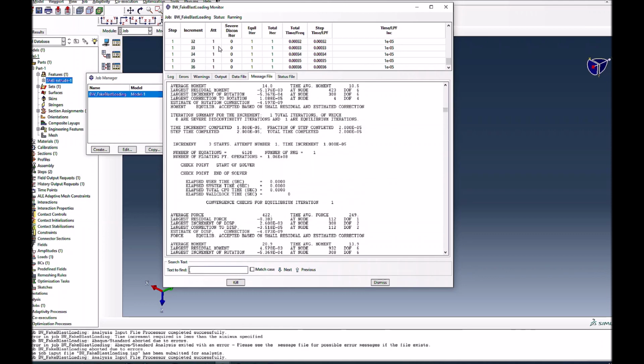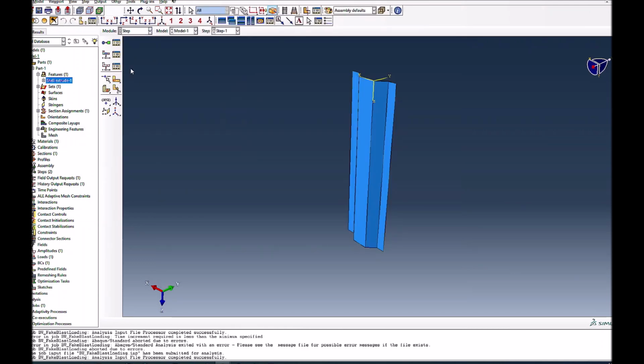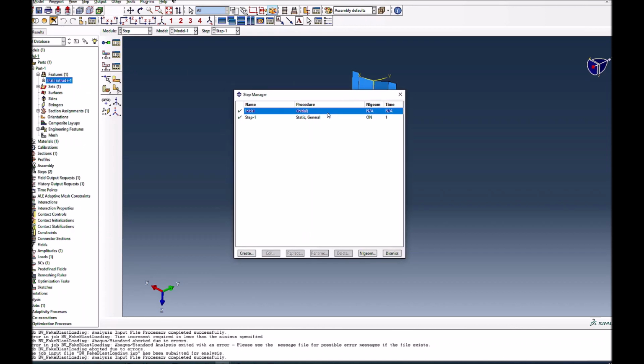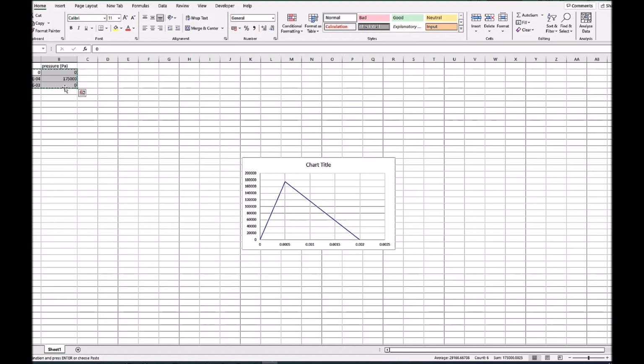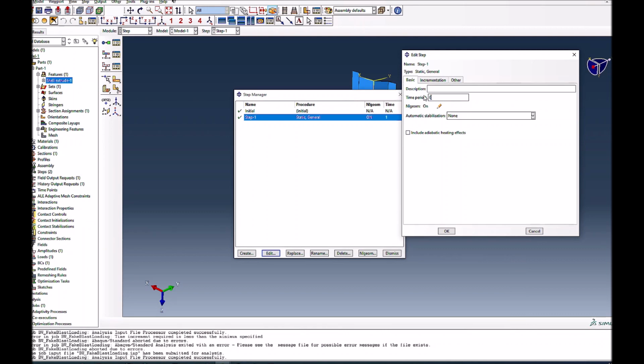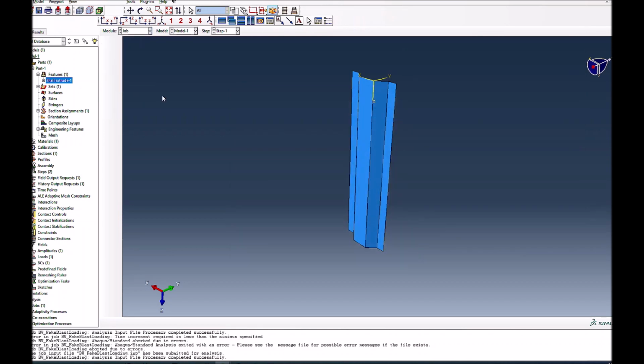As soon as we increase the thickness, it basically started working properly, and you can see it's going fine now, and it has to go up to, but I think we can stop it here. I think I didn't define the total step time correctly. So this total time should have been the same as what we have here, which is 2 exponent minus 3, right? So it should be 0.002. By that time the blast has completely disappeared, but in this case we keep it running.